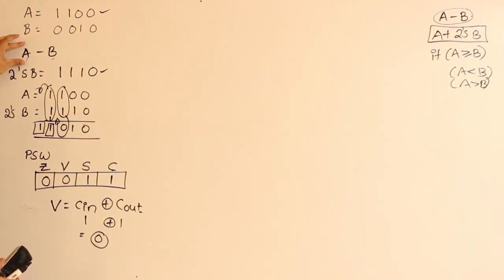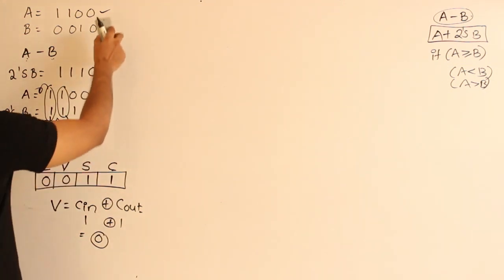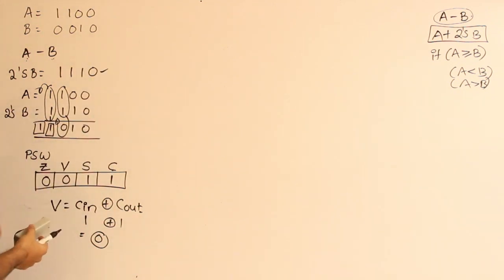So when you apply that compare operation, which I have shown you earlier, compare a and b, the result of a minus b will not be stored anywhere, but the flags will be stored. Now depending on these flags, we are supposed to find out whether a is greater than b, or a is less than b, or a equal to b. But then it depends on how you interpret the numbers. There are two ways you can interpret these numbers. Whatever way you interpret it, the CPU operation is always going to be the same, but your interpretation can be different. Either you can interpret them as signed numbers or unsigned numbers, but for a CPU both are considered the same and the same thing will happen.